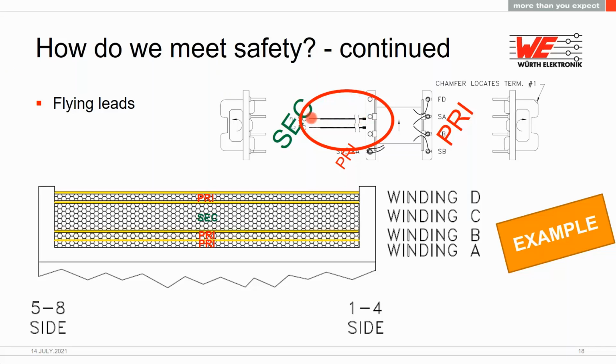In this type of method, we would also use the special extruded insulation for these flying leads. The idea being that the end of the flying lead will be stripped and tinned, and then our creepage path from this critical location then follows the remaining extruded insulation back to the rest of the transformer, whether it's the core or the magnet wire terminations or the winding area. One important point to keep in mind is that these flying leads must be manually inserted in the PCB. This is a highly manual process and can add to the cost of your PCB assembly process.